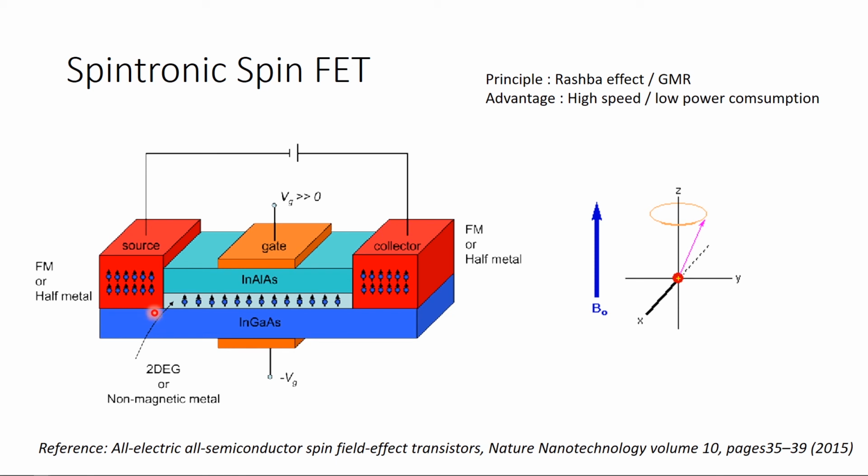If the spin up electron can transport coherently across the channel to the collector, since the magnetization direction is parallel to the electron spin, the electron can go across easily. However, if we impose an electric field across the channel, the accelerating spin electron in the channel will feel a magnetic field, causing the spin electron to go through precession. If the electron under precession flips, the electron will become anti-parallel to the collector, causing large resistance. Therefore, we can control the transistor with the gate voltage by the spin method, which can achieve the same result as the MOSFET.